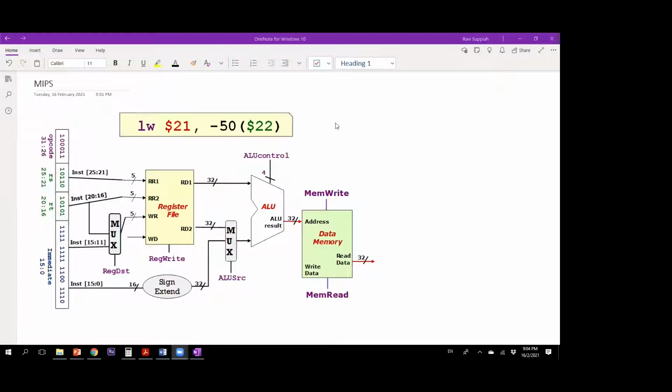That is, to put it very simplistically, the idea of a single cycle processor. So what we are covering is what we call a single cycle processor. That means in one clock cycle you execute one instruction. That means your processor speed is limited by the slowest instruction.